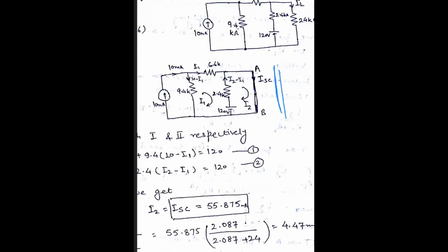Okay, current source is activated, voltage source is activated, and load resistance is short. These things are to be taken care of. So when the energy sources, current source and voltage source, are activated, then the direction of the flow of the current will not be the same as was used to calculate the Norton resistance.